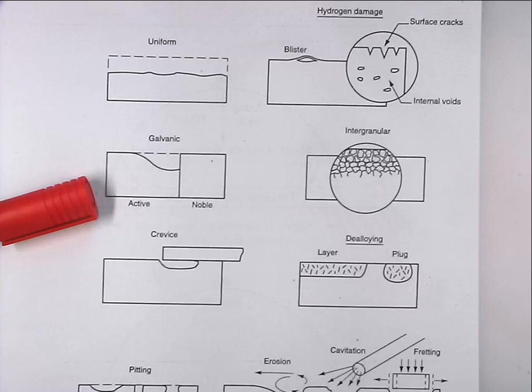The steel tubing has more or less corroded away because the brass as an alloy is less anodic, and you've got build-up of a large amount of corrosion product on the inside of the tube, which has started to reduce the supply to the property.